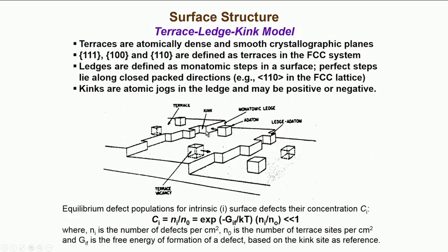Now, when crystals grow, they develop certain contours, certain morphology. If we divide the entire realm of solids into two major categories, metallic crystals and non-metallic crystals, then for non-metallic crystals, which could very well be ionic crystals, we do see a ledge growth mechanism in operation. In other words, since the atomic bonding energy is very high in such ionic crystals, the atoms usually will not be able to come and sit anywhere on top of the existing surface.